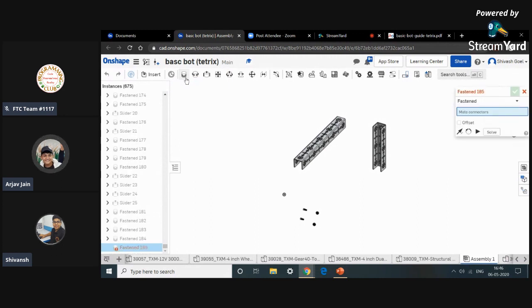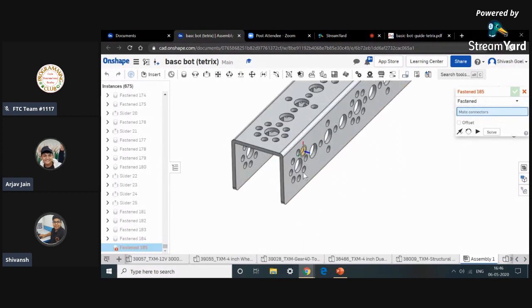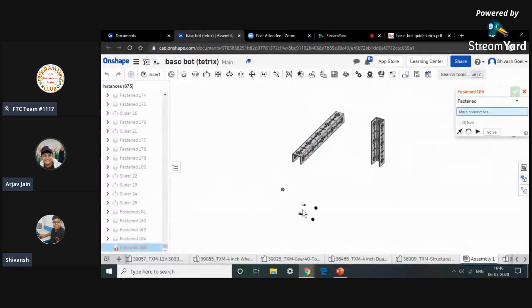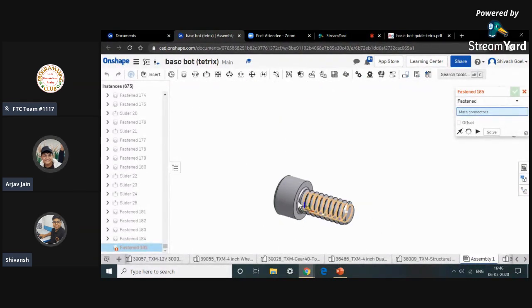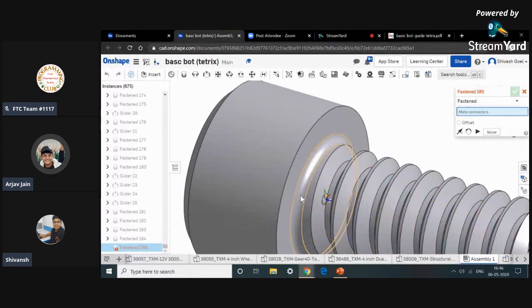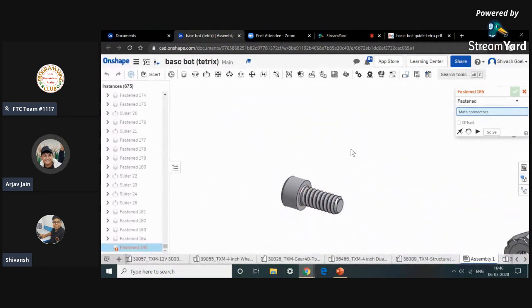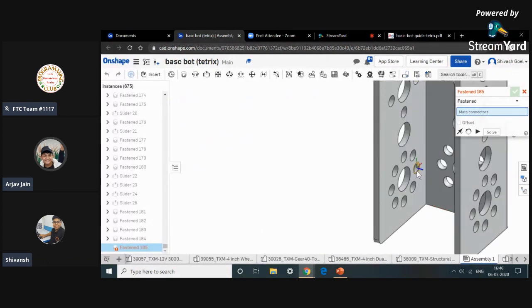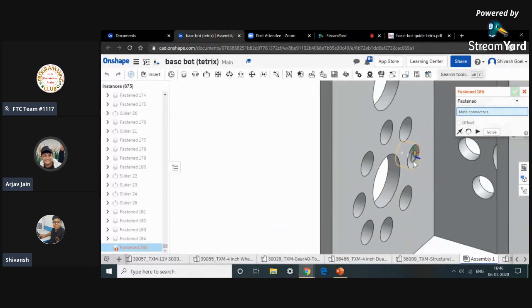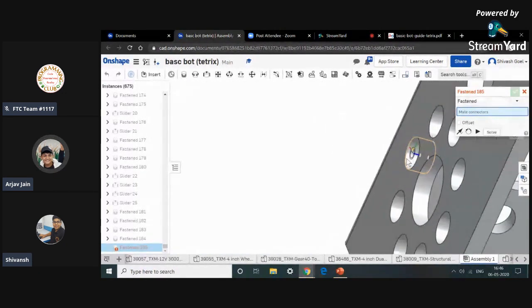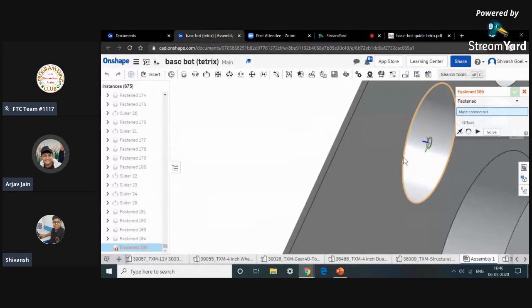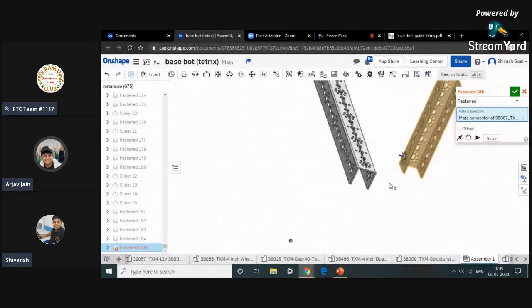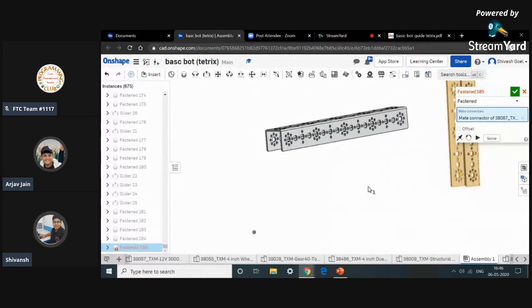You have to select the faces of the parts or objects you want to connect. The first object surface that has been selected will move to the second object surface. If you have made a chassis and have to attach a wheel to it, you have to select the wheel surface first, not the chassis surface, because otherwise the arm or the channel will move to the wheel, not the wheel to the main chassis board. This has to be clear in mind before you start.